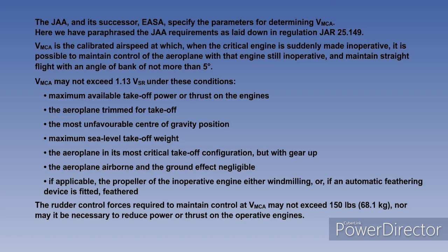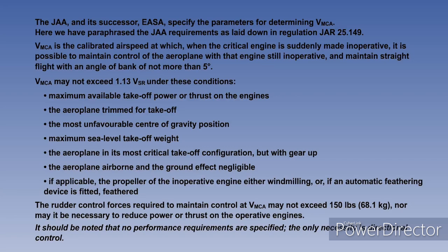The rudder control forces required to maintain control at VMCA may not exceed 150 pounds, nor may it be necessary to reduce power or thrust on the operative engines. It should be noted that no performance requirements are specified. The only necessity is directional control.